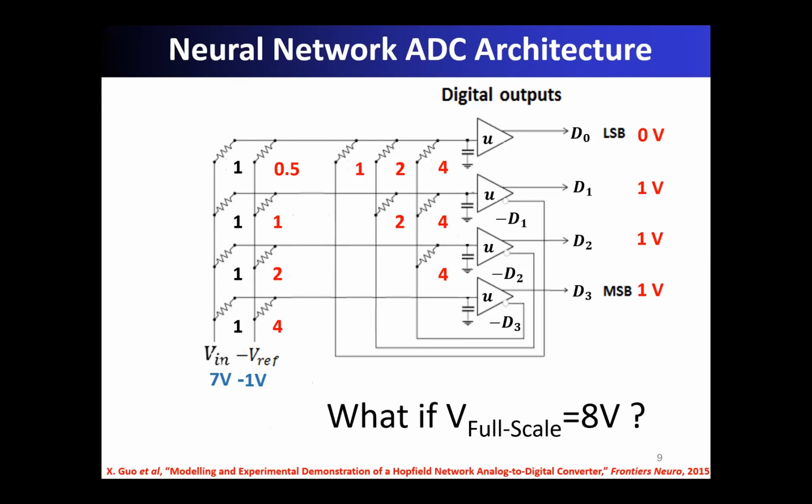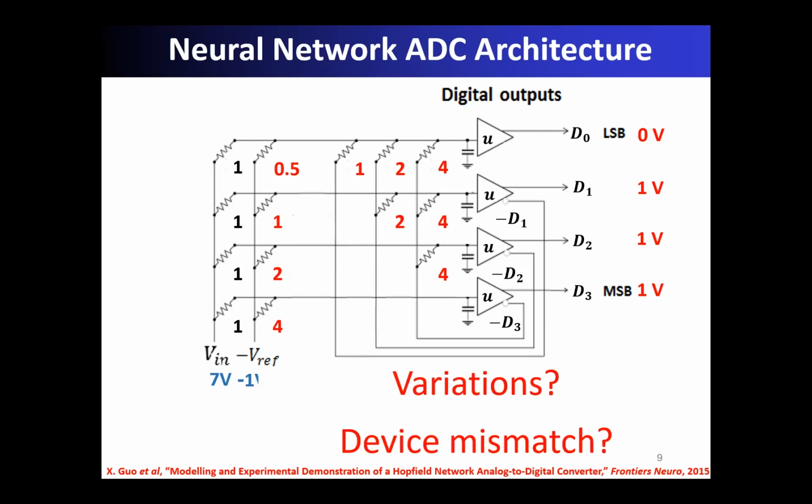So this network is deterministic, but the real-time silicon is not deterministic. It has a lot of process variation and device mismatch, which make the problem non-deterministic and challenging to model. So how could we compensate for these on-chip device mismatches? We need a variable resistor that could be updated and reprogrammed on-chip using a training algorithm. So we need a variable resistor, which is called a memristor.